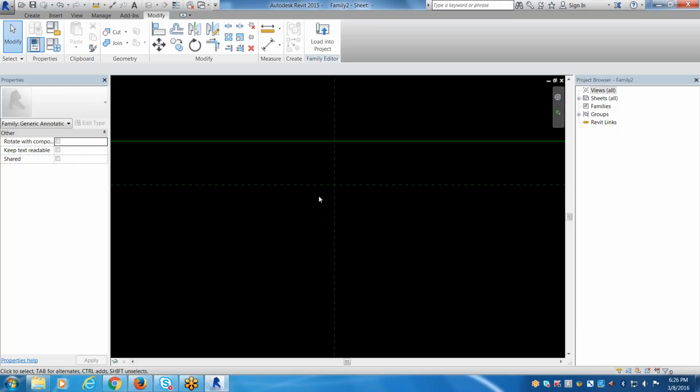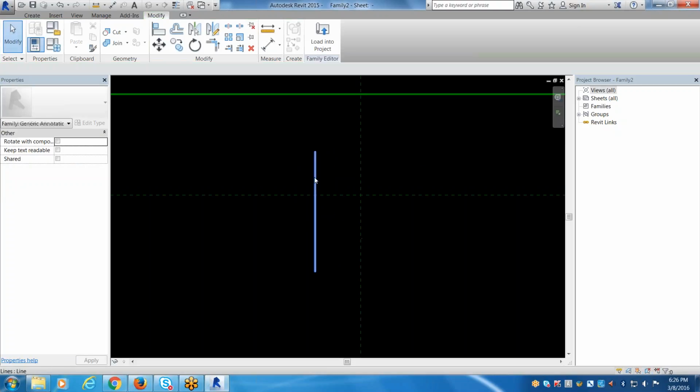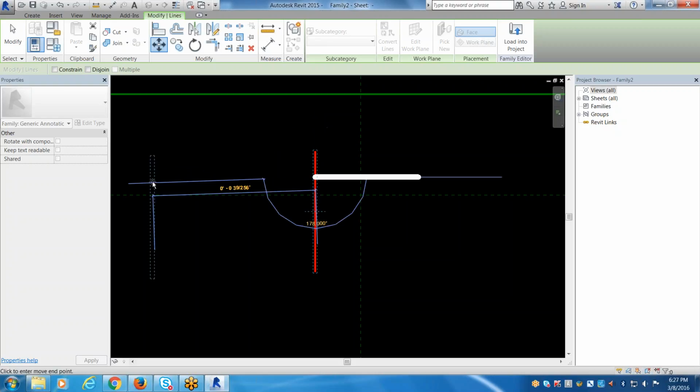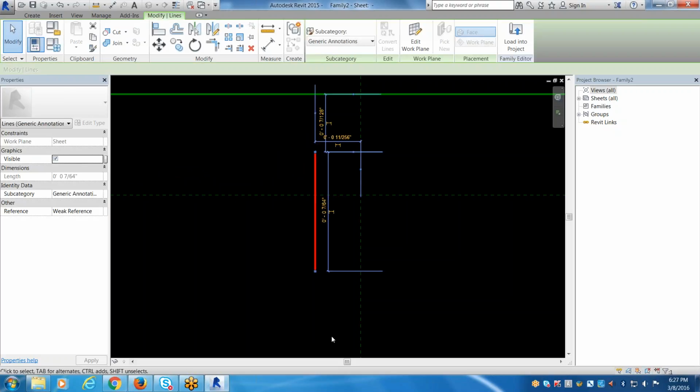What that also means is, let's say I draw this line here and I move it, I can't draw anything or modify anything under a 1/32 of an inch, or move something a 1/256 of an inch over. If I did need to move it that far, I'd have to move it out here and then move it back, including that 1/256. Does that make sense? It's kind of a pain. It's a big limitation. Nothing you can do.